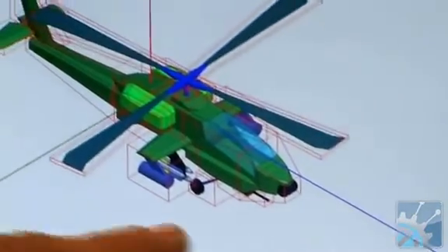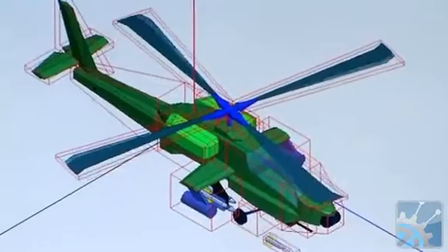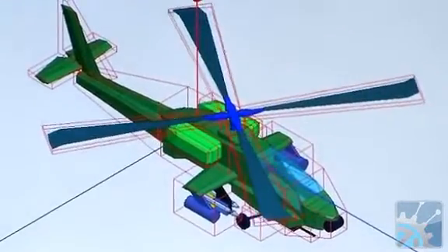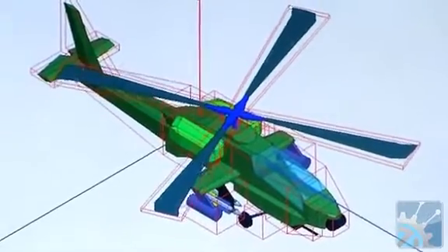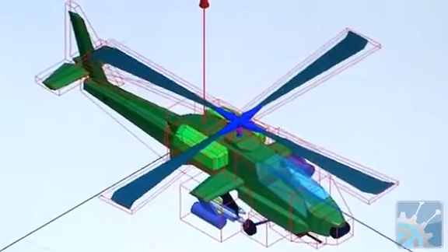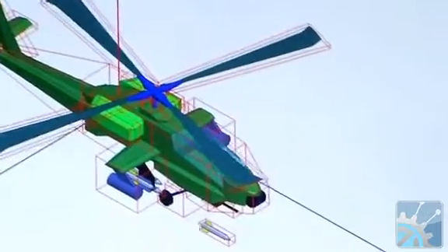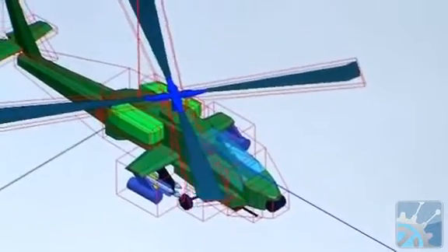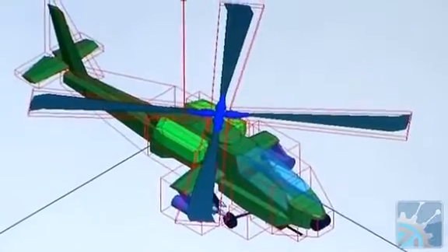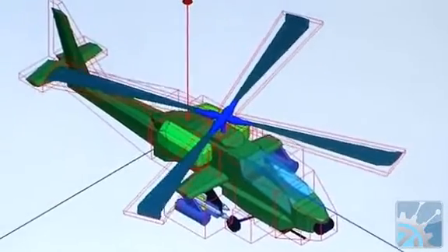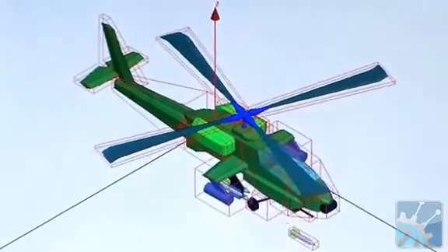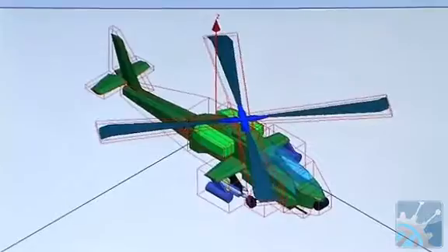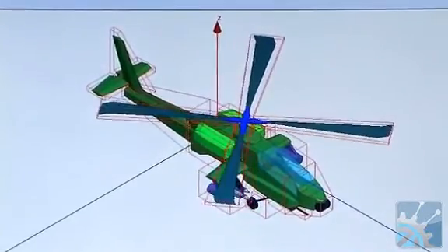You've got a finite element domain around the helicopter, one around the missile, and then of course it's all being parameterized and modeled with respect to the rotation of the helicopter blade. Very efficient. In 14, we're going to extend this where if that missile is entirely metal, you don't have to have the surrounding air volume. You can use an integral equation solution directly on the conducting surfaces of the missile. A great example where this could be used would be, say, in a dish antenna analysis, where you could use HFSS for finite elements for the horn feed, and then an integral equation solution for the dish.